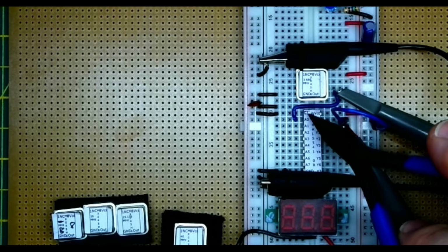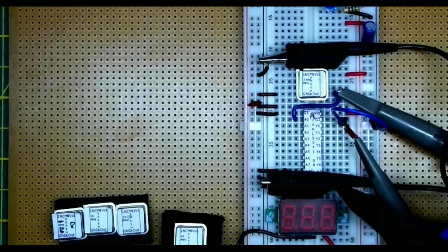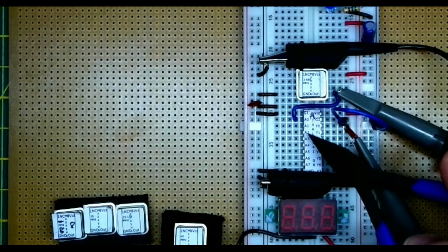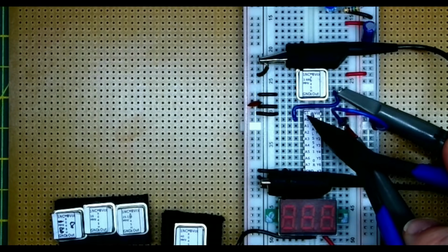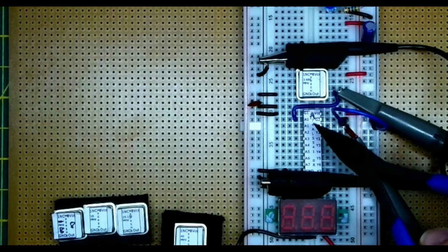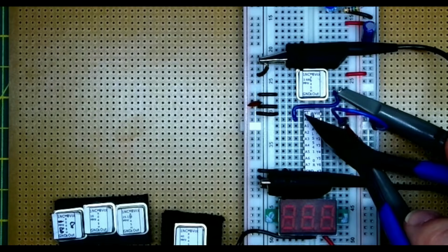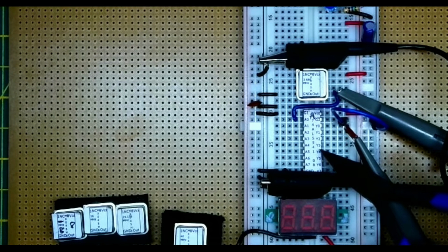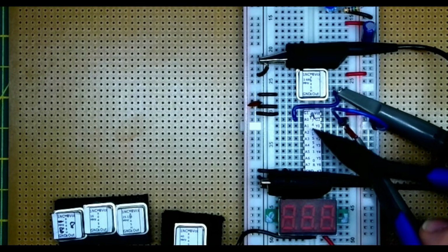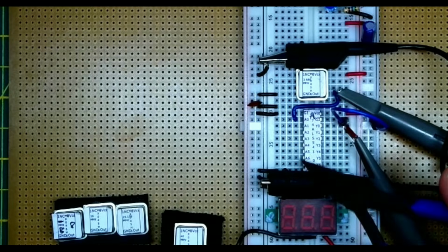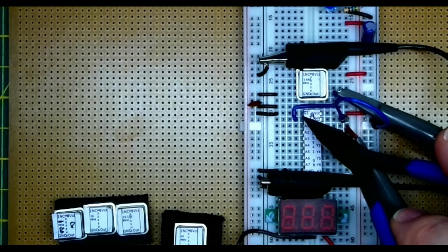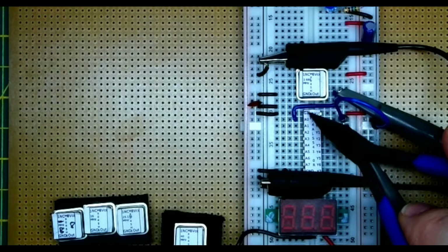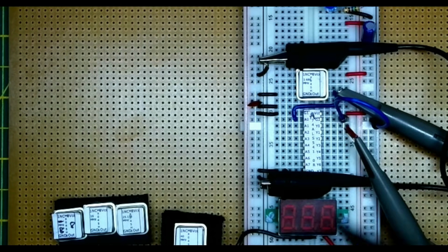What I tend to do with these chip labels, by default, a lot of the data sheets start at 1 and go to 8. However, when you're dealing with a lot of digital signals with microprocessors, since we're always dealing with 0 indexed, I tend to start the chip labels at 0. And sometimes, depending on the breadboard layout, I might also have it going from 7 down to 0. So I have two layouts for the chip labels, both starting at 0, but one has 0 at the top and the other has 7 going down to 0.